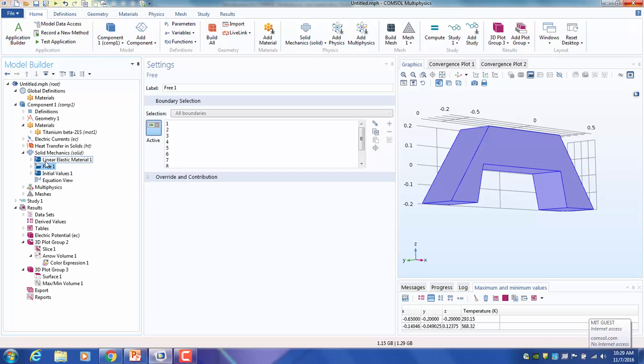So how do you have a unique solution? You need 6 constraints. A typical way is people fix one point, which eliminates 3 degrees of freedom. Then at the second point, you say it can only move in one direction, so in case the structure expands, it will still stay on the same axis. That eliminates another 2, and then there's another rotational one. So on the third point, you say it can only move on this surface. That's how you eliminate the 6 degrees of freedom.